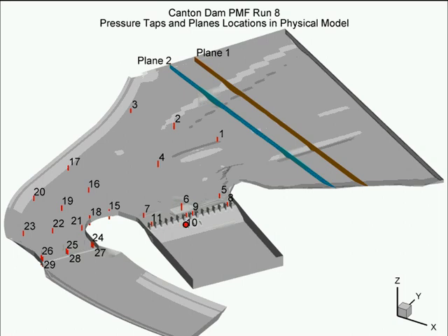This is the existing structure down in this area here, right around the number 10. That's where the flow passes through the existing dam. That dam does not have the necessary capacity to pass the newly calculated flow, if you will. So a fuse gate spillway is being constructed on the side here, right in this area here. It's going to pass the extra flow without exceeding the allowable water surface elevations.